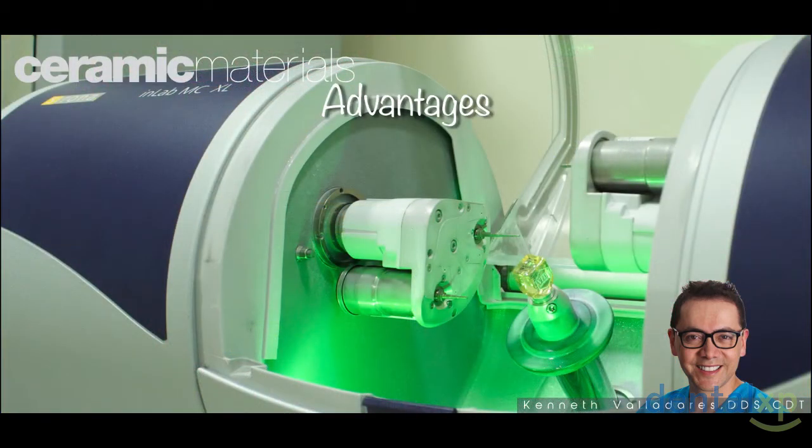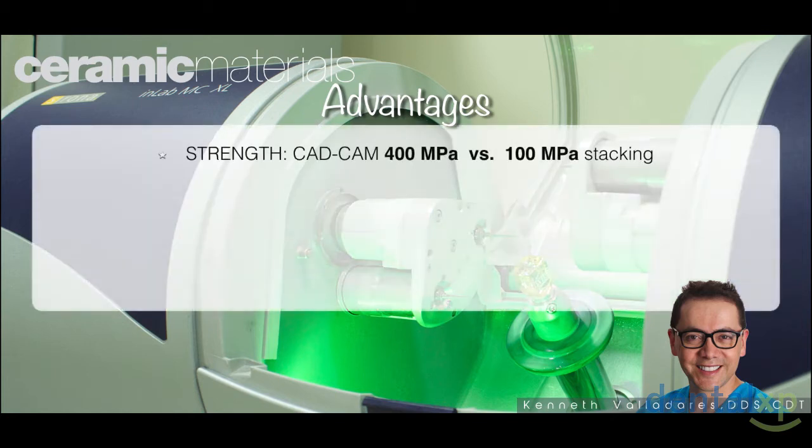What are the advantages of working with CAD/CAM or monolithic techniques? First, greater strength. The CAD/CAM offers 400 megapascals, while stacking materials only offer us 100 megapascals. This is because the blocks are industrially pressed by the manufacturers, which makes them more resistant and compact.